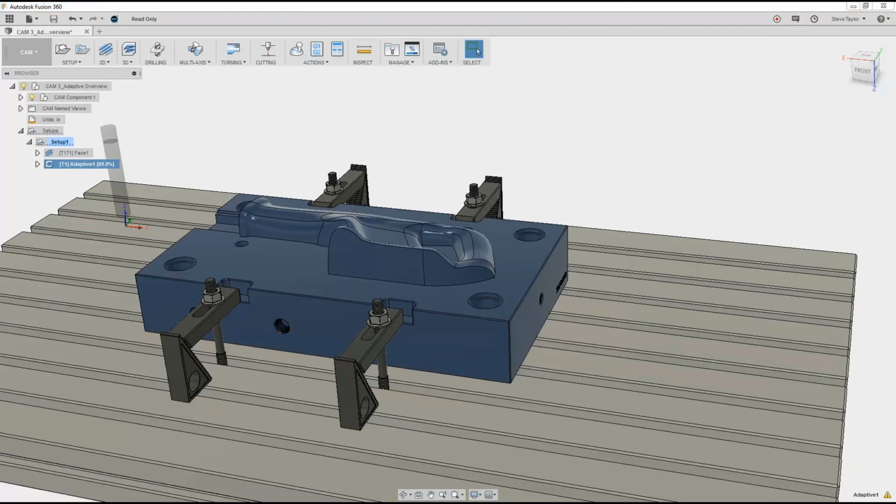So hopefully, very quickly, it's building it up. You can see the status telling us it's generating the tool path. Because this tool can come down as low as it does, you can see the tool path starts by clearing most of the geometry on the first level. Then it will start working its way up the part. The long yellow sections show the full retract that we have between transitions. You also have the option of not having to fully retract, which we'll take a look at for finishing.